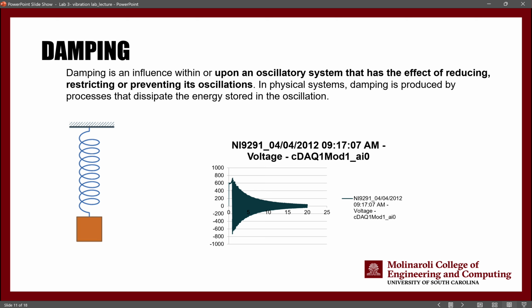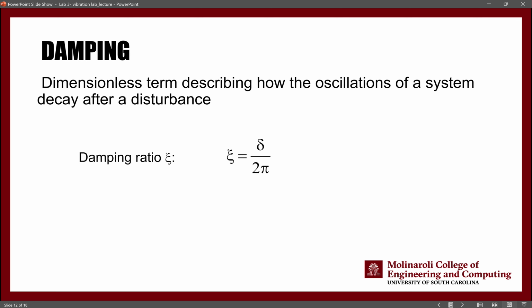So essentially, we have a couple of strain gauges installed on our beams. And when you start vibrating the beam, the strain gauge is going to record a strain value, right? Meaning that higher the vibration, higher the strain, right? And as your vibration dies, you are going to see a lower and lower value of strain. This is a damping vibration. We can use this data, the strain data, to do damping ratio calculations.